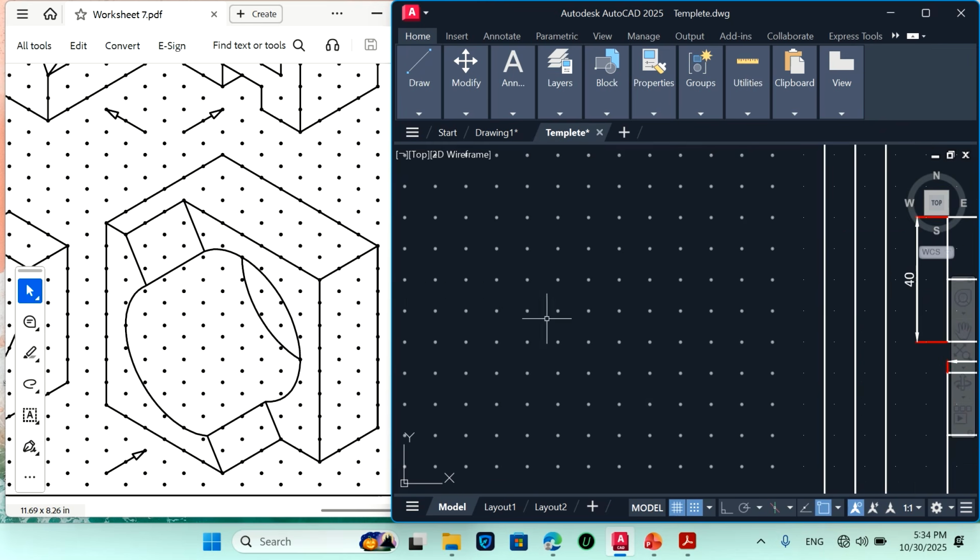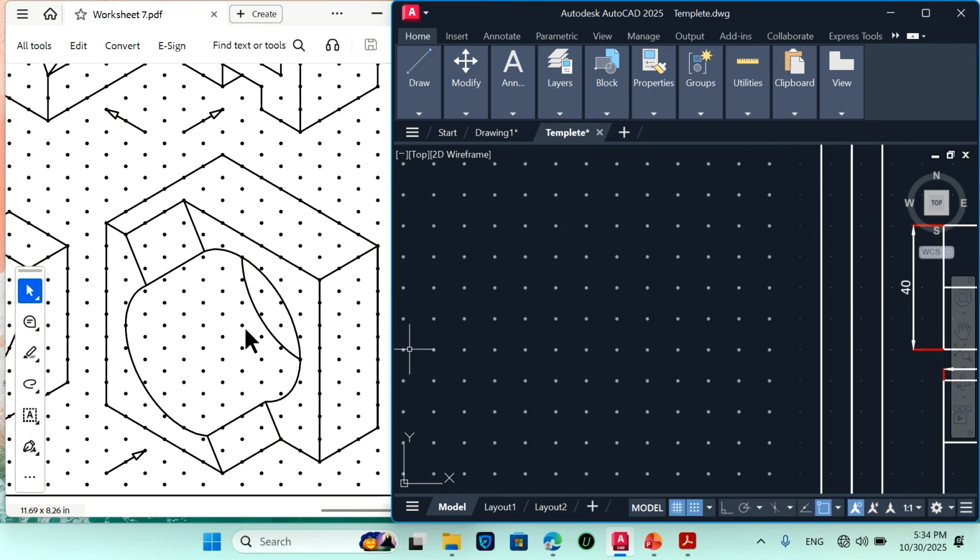Now if I go to the front view, first where to start? This is the principal surface, I will draw this. You see the dimensions: 1 2 3 4 5 6, 60 mm, and height is 1 2 3 4 5 6 7 8, 80 mm.